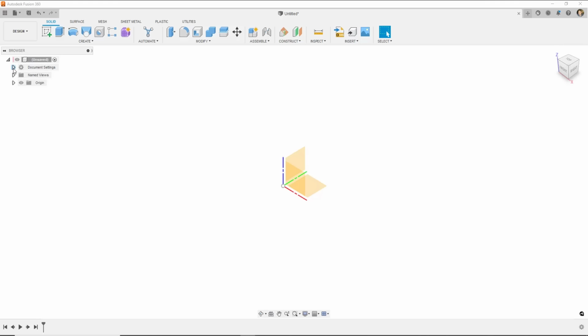The only thing you're going to do really in here is under document settings. For this specific document, you can set your units, okay? So if you click on this edit, then you can change your units. What do you want to draw in? This course is all going to be in millimeters, but if you want to work in inches, it's up to you.